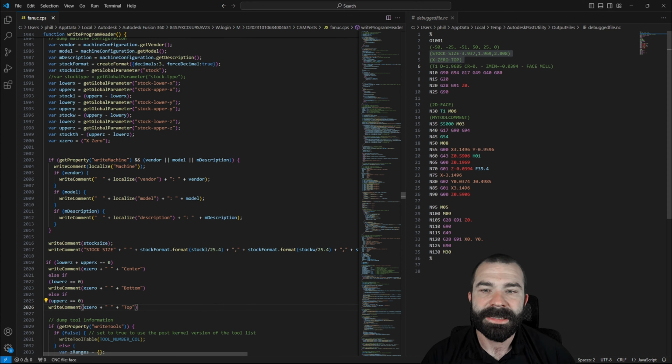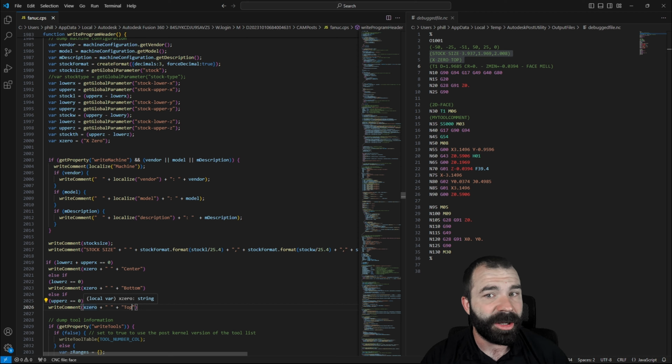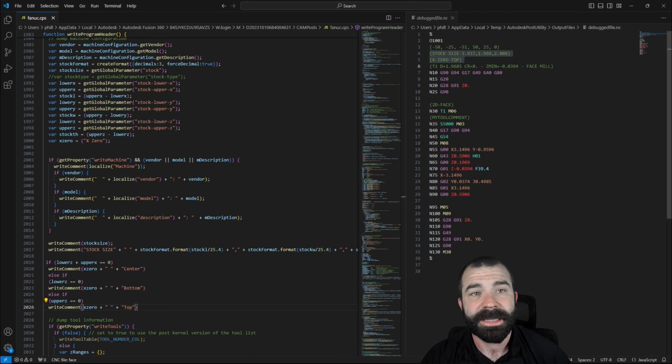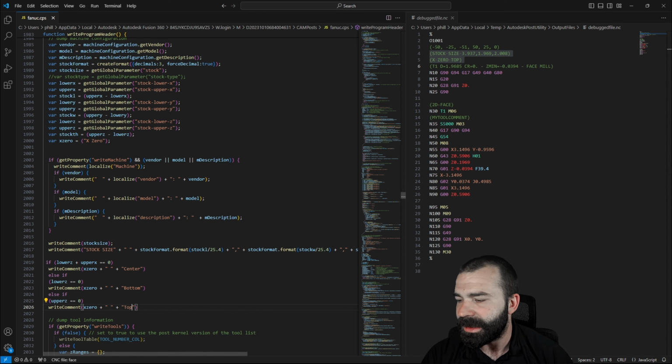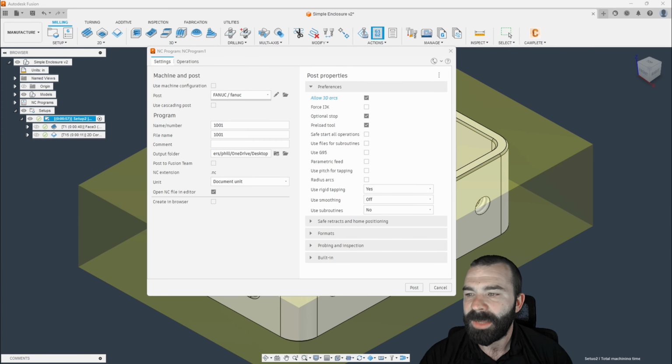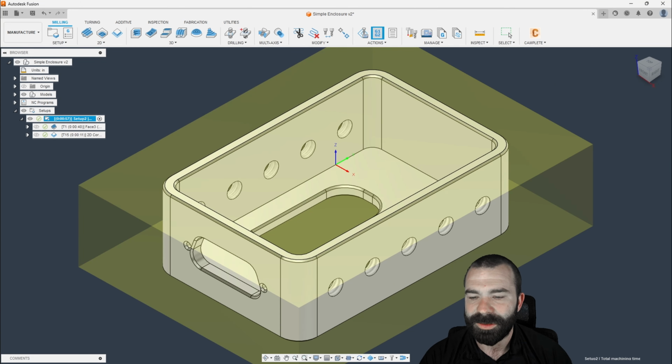So as you're seeing here, because we did define an x0, but I'm using the Z callouts, we are now getting a top callout versus a bottom or a center callout, right? And that's very easy to control. We could actually stack this up just about as much as we want. I'm also going to jump back to Fusion and we're going to use the actual x-axis now to populate this information to make sure everything is good. So again, we're going to hit save. We're now x0 center. I'm going to pull up Fusion 360 and let's post some things out to play around with this.